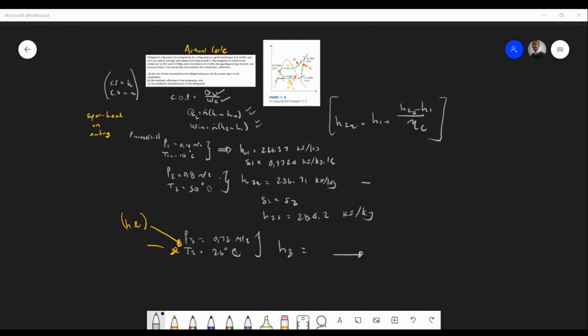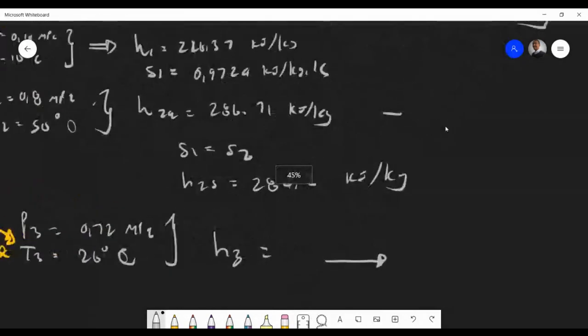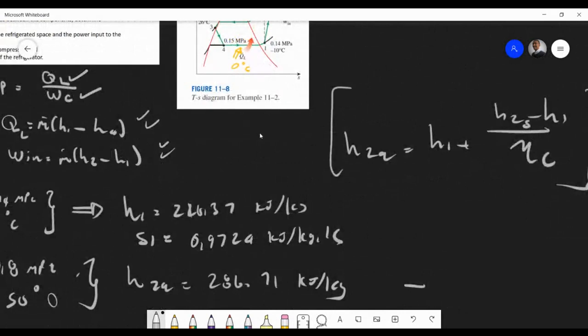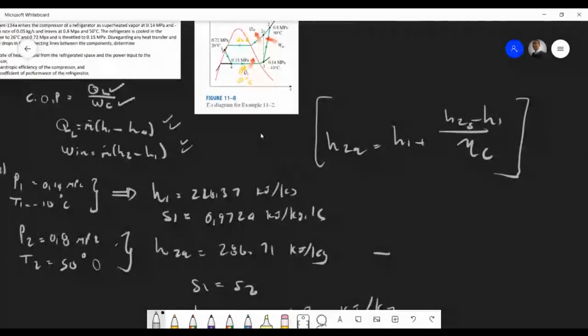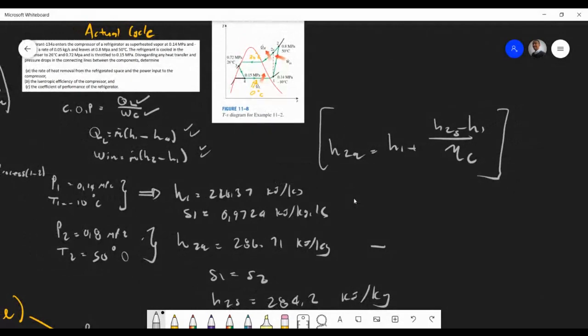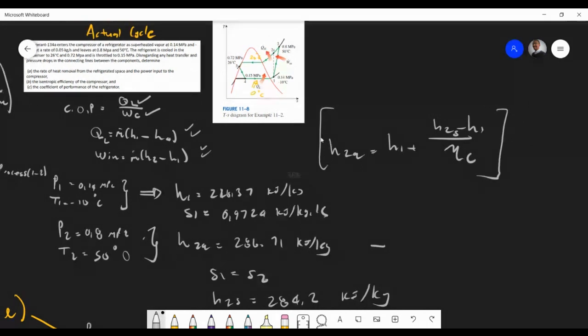The reason why you're saying we should ignore the pressure there, is it because I'm looking at that TS diagram where you got your H3 at point 3, but it's also the same as H4, I think? Yes, that's correct, point 4. And the reason why is because we're throttling, we're not losing any enthalpy. It's approximately the same. I'm just making you aware.